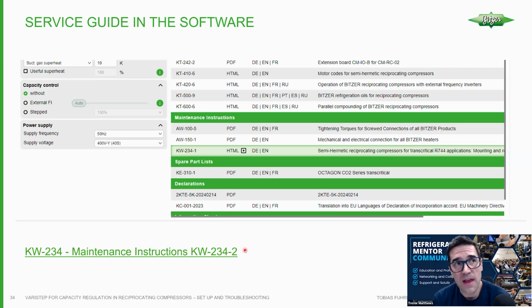Yeah, definitely. And so, for example, if someone has never come up to one of these capacity control compressors, when they put the solenoid on or when they unload, the sound changes. So can you talk a little bit about that? Because that's pretty important. The first time I ever saw a capacity control, or even block suction compressor, you could hear it change. And if you've never seen that before, it kind of gives you the idea that maybe there's something wrong with the compressor. Do you want to talk a little bit about that when it's loading and unloading?